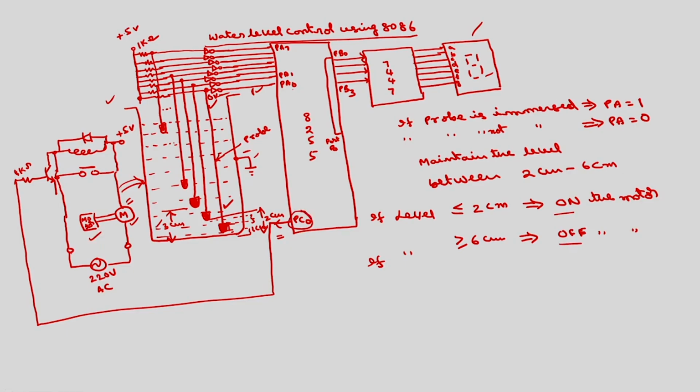Okay. So you see the hardware setup, the connection from 8255 to 8086 we are not showing because we know how to interface 8255 to 8086. So with this assumption, what will be the program for this? Here we are using all the 3 ports, port B as output port, port C of course only one pin as output port, port A input port. Let us assume that I want to operate everything in mode 0.